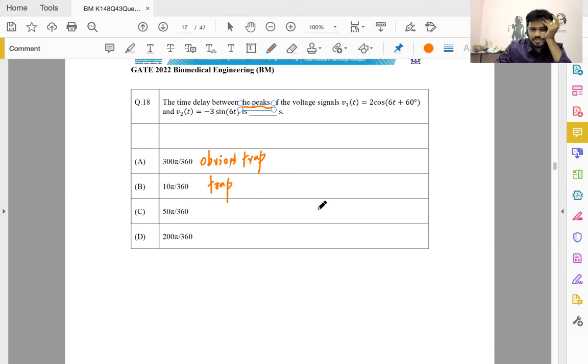Best way to look at this is as a phasor diagram. Okay, in the complex plane, we have real part, imaginary part. Notice in the real direction, this corresponds to cos omega t. Okay, we measure angle, positive angle this way. Okay, positive time. Any angles positive this way. And this corresponds to imaginary part, specifically, negative imaginary axis.